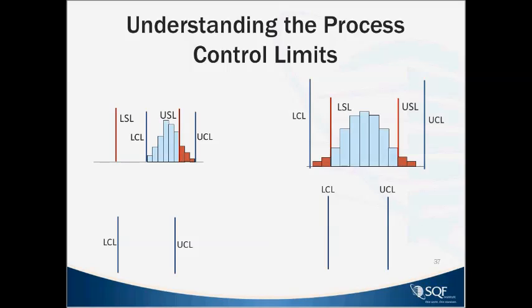Here now our goalposts haven't changed; they're there. But in this example, our histogram, or our spread, is now larger. You can apply those control limits on the outside because we know they're always near the outer points of our histogram. You can clearly see that the process is centered, but again, we're making out of spec product on both the lower side and the upper side.